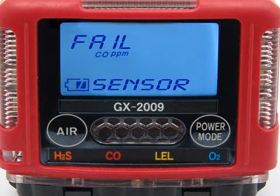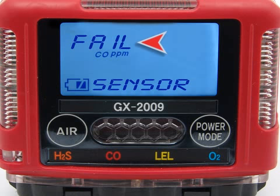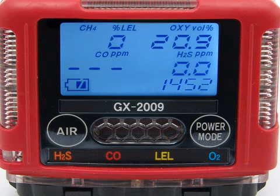If the GX-2009 experiences a sensor failure during startup, a screen will display indicating which sensor has failed. If you wish to continue, press and release the power mode button to acknowledge the failure. The instrument will then proceed to normal operating mode. Once in normal operating mode, the gas reading for the failed sensor will be replaced by 3 dashes. The failed sensor should be replaced as soon as possible.